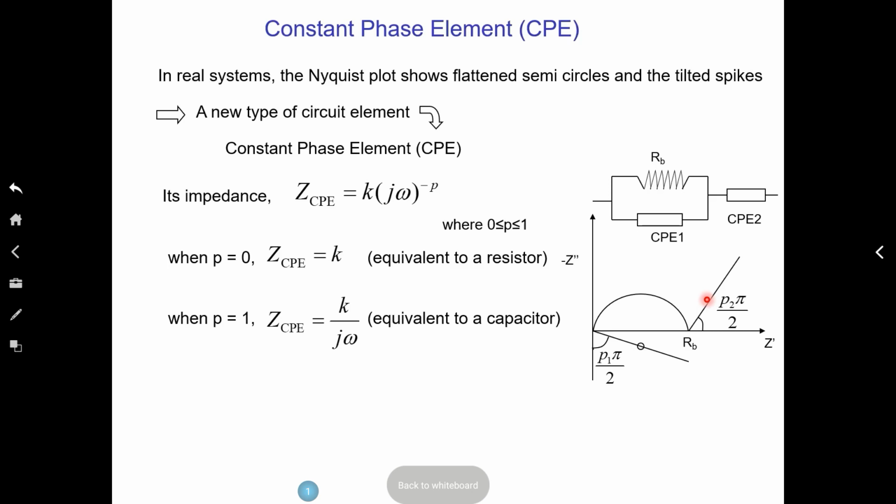Something like, let's say you take your strip of zirconia, which is an oxide, and you put a platinum ink on it as a lead. Platinum ink, you have to cure it, it will burn out the organics and so on. Then you will get a porous layer.